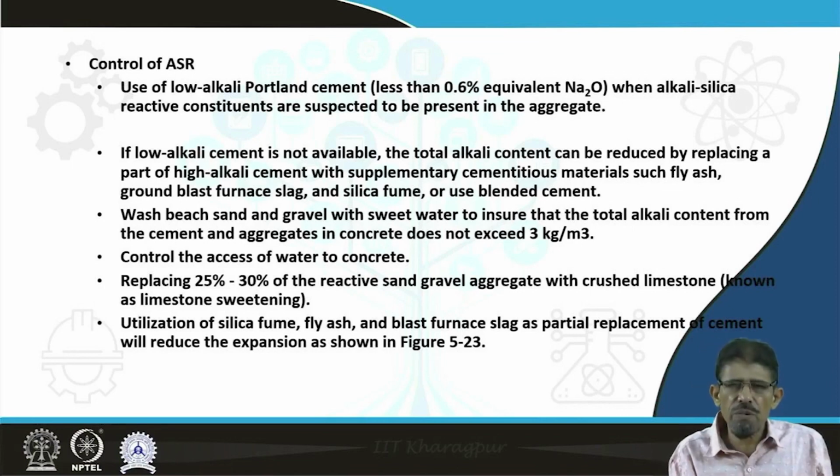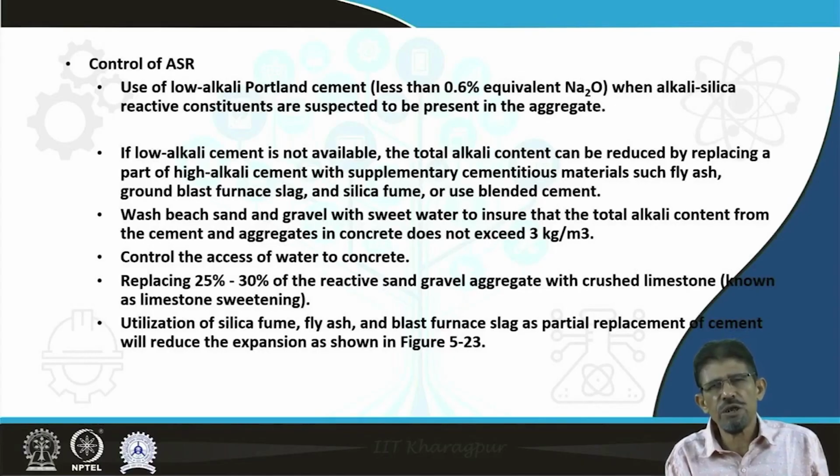Very simple, we are going to pinpoint three steps. One is either we reduce the alkali in cement, or we reduce the availability of water, if fortunately or unfortunately some reactive silica-containing material is available in the aggregate.